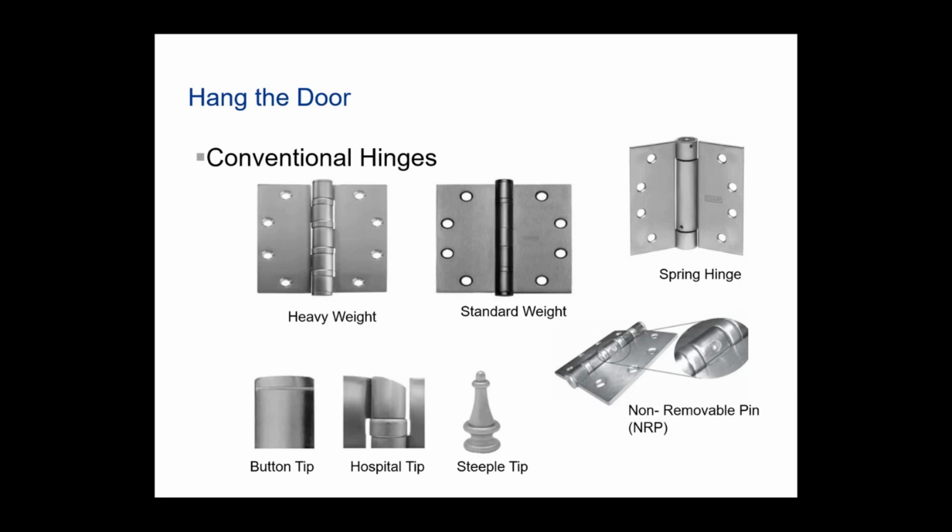Once that pin is removed, if you open the door, you can then move that door out of the frame and leave the one leaf of that hinge on the frame, one leaf on the door, and it helps with, or some would say that it helps with the install process.